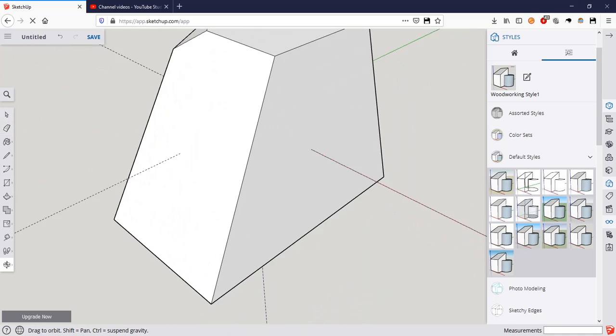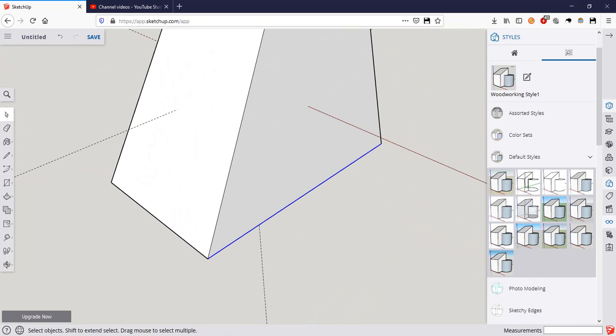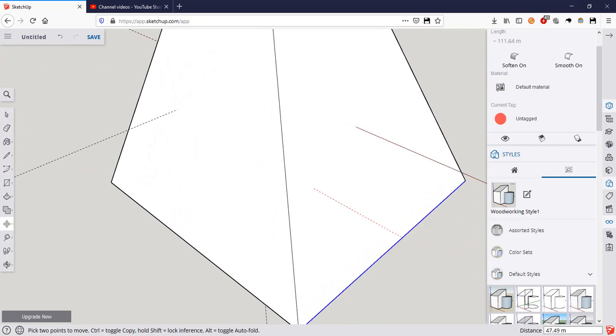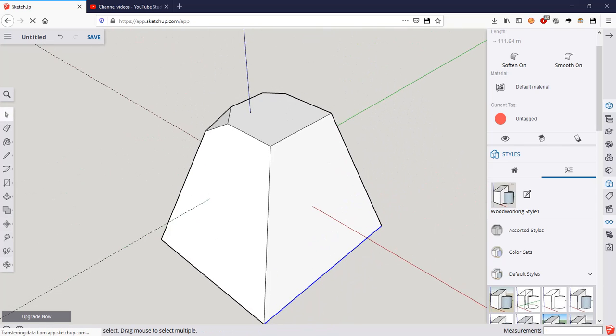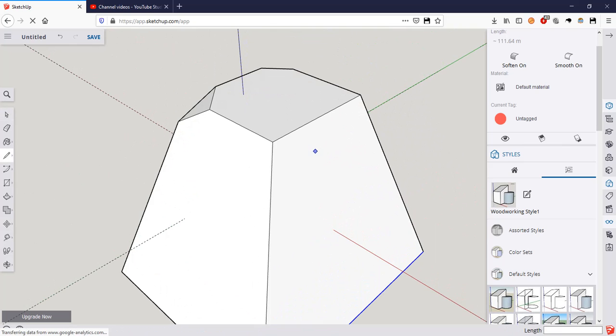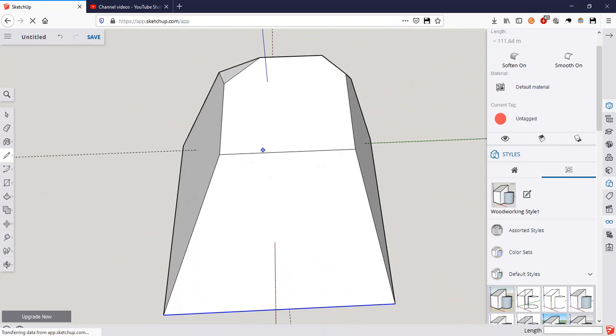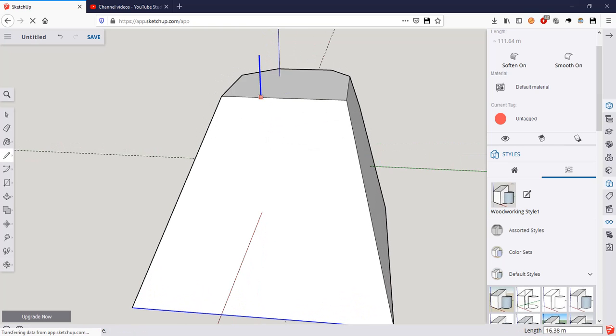Ooh, I don't like how it's flat here. Let's grab this line. Hit M for move. Let's move it right out here. Okay, then what we're going to do, L for line tool. And notice how it says on face. That's very important. If you hit the up arrow, we're not on the face.